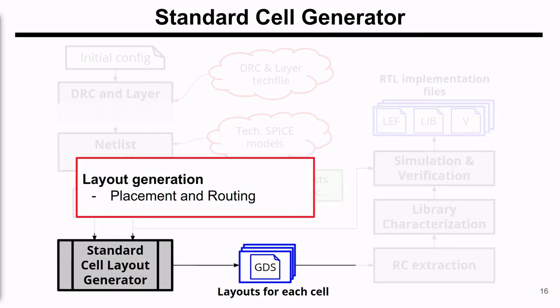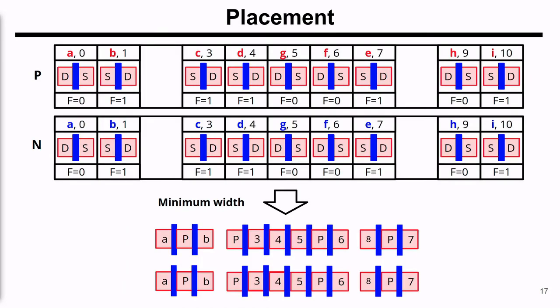The main problem with these standard cells that we want to focus on and solve is the standard cell layout generation. Having the schematic in netlist form from the previous step, we perform placement and routing of the designs. The main focus of the solution is a placement algorithm in double row for standard cells. For this algorithm, we define a series of rules and constraints for finding the minimum width position of all transistors inside the cell. Also, with the purpose of outputting a layout, this solution needs to optimize for net congestion for routing purposes.